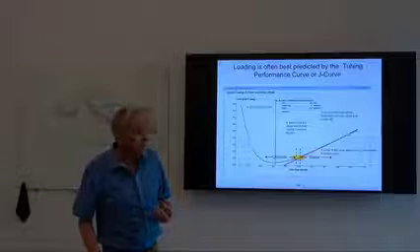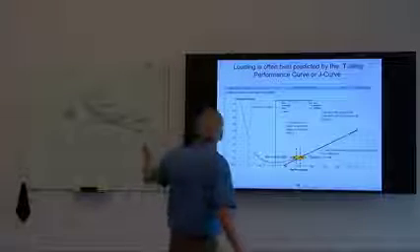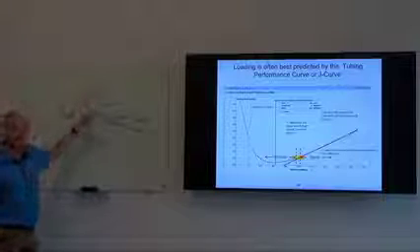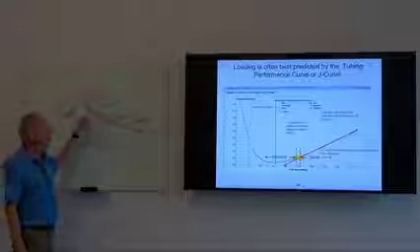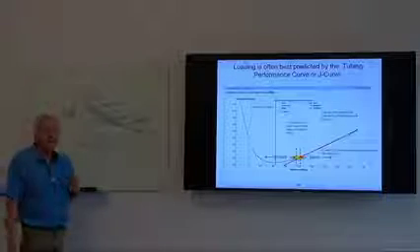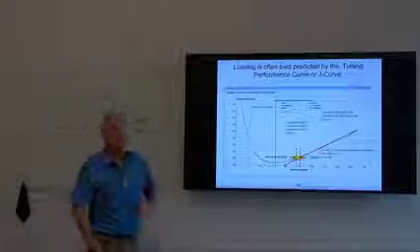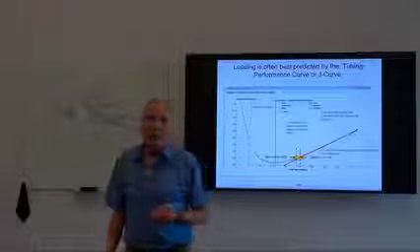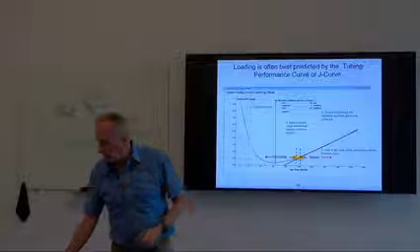This is very important, both from the standpoint of when we would expect liquid loading to begin initially in a free-flowing well, or even the instantaneous rate that we would expect to see liquid begin to load in the afterflow portion of a normal conventional plunger cycle.